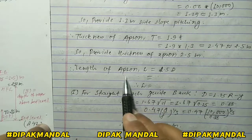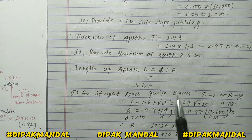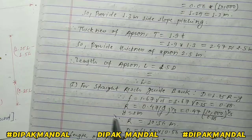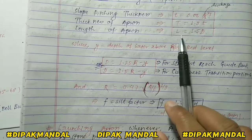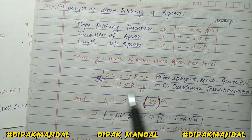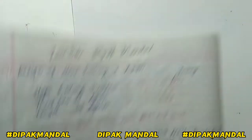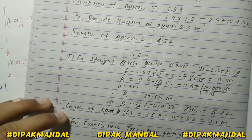Now we have to calculate length of apron, that is L equal to 1.5 times D, and for this we have two different conditions. As we discussed, the length of apron can be calculated equal to 1.5 times D, and the value of D is taken 1.25 (R minus y) for the straight, and D equal to 1.5 (R minus y) for the curvilinear. So we have these two conditions. Okay, and we have to calculate these two conditions individually.